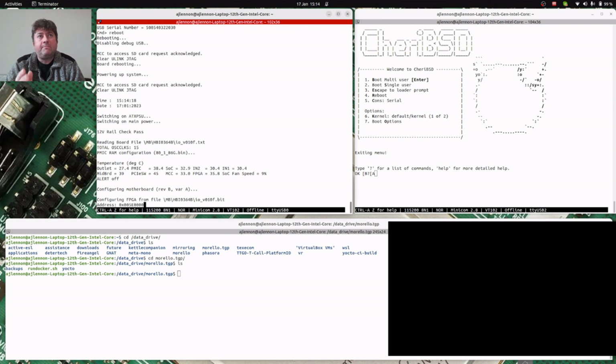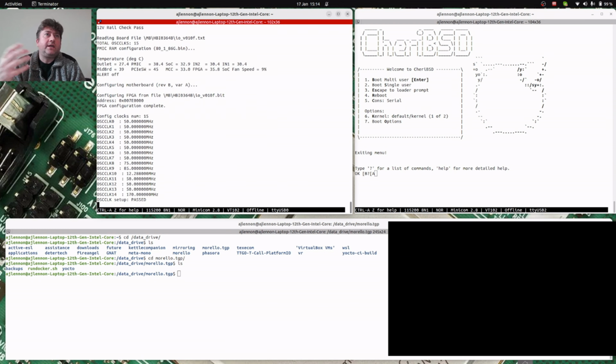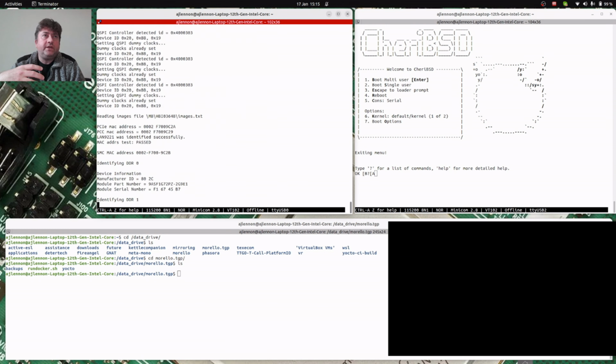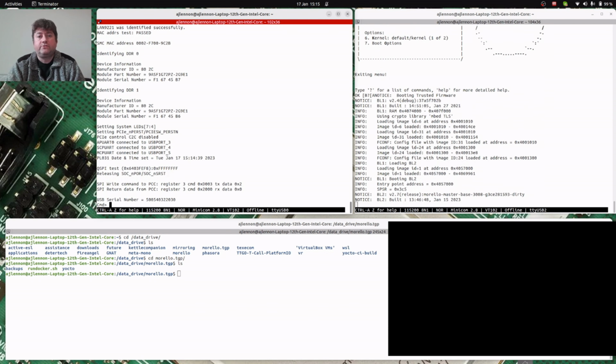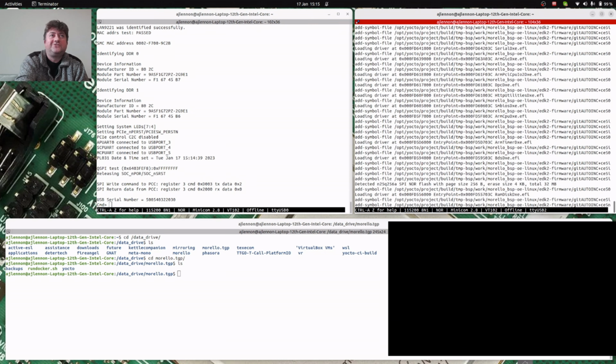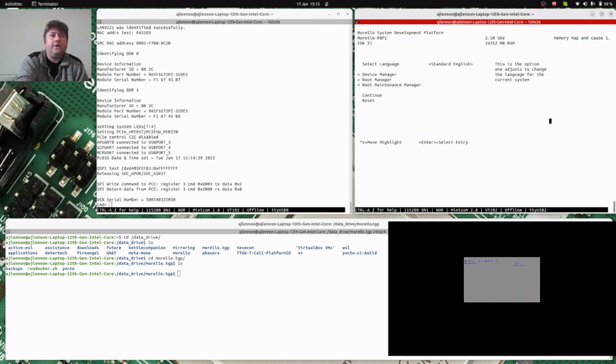And then I'm going to take a step back after that, and show you how we stepped through getting that code from the Good Penguin repository, building it up locally and deploying that onto the USB stick. So I just need to jump in fairly quickly here to try to break out of the automated bootloader boot. And there we go, and we're now into the equivalent of what you might think of as a basic BIOS. And I can go down through that into the boot manager.